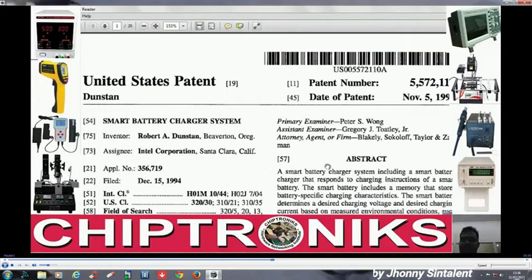Whereas if you talk about other batteries, they don't have such a mechanism to transfer such data. So the mechanism of transferring data, and that too updating, right? Updating with activity. Like if the notebook motherboard is running graphic intensive work, then in that case the heat generated in the notebook motherboard would be more. Then the battery will send information to the charger that it requires a larger charging voltage, because we'll talk about why a larger charging voltage is required when the temperature increases in a notebook motherboard.